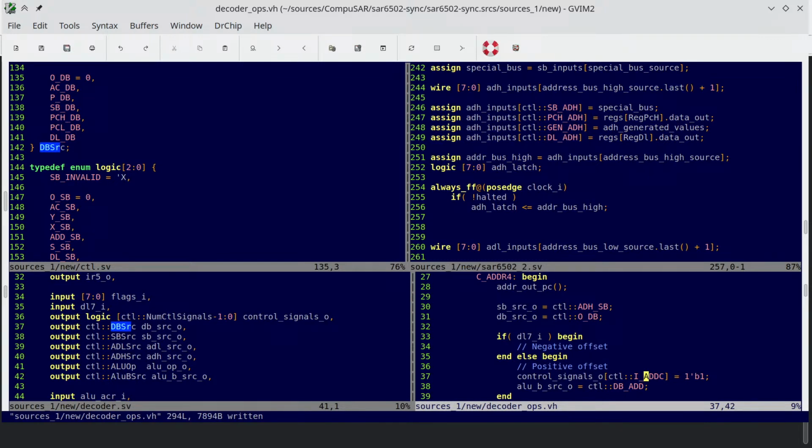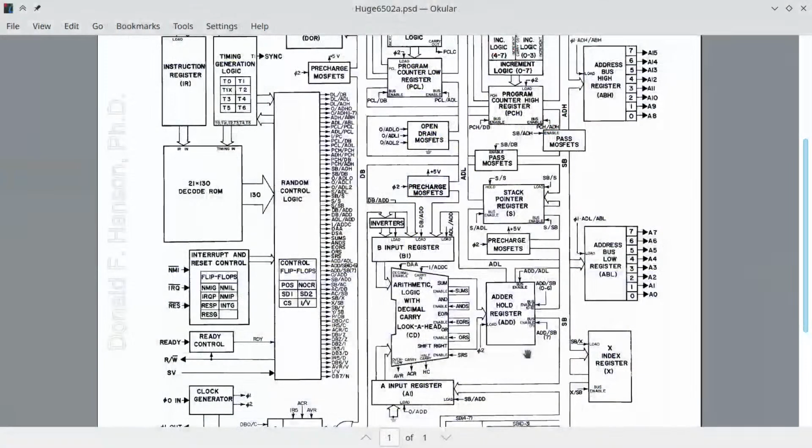How about subtracting one? Well, we're using 2's complement logic. In 2's complement logic, minus is reversing all the bits and then adding 1, which means that -1 is a value with all the bits set. We already have the data bus with all the bits clear.